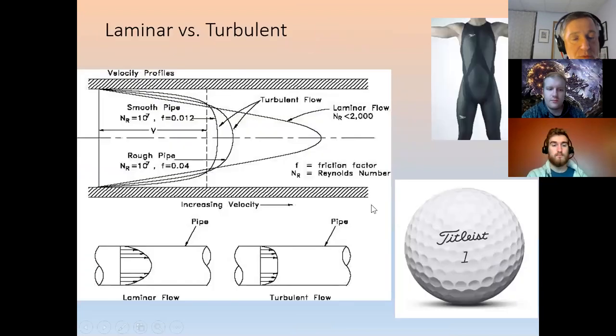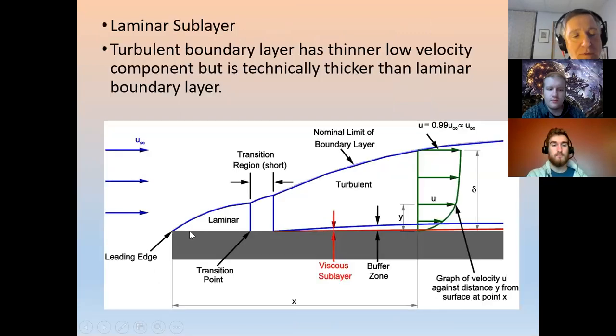So when we look at the flow over a plate, you'll see that again. So laminar and turbulent flow, which we spend a lot of time with. This is a good diagram. This is a flow over a flat plate. So it's sort of like the smoke stream that you just saw. When you initiate flow, you do get a laminar portion of it. And then if it's at a high Reynolds number, over 2000 at least, it will trip to a turbulent boundary layer, but it does take some time to do that. If it's a low Reynolds number or low flow, you'll have a laminar flow throughout.